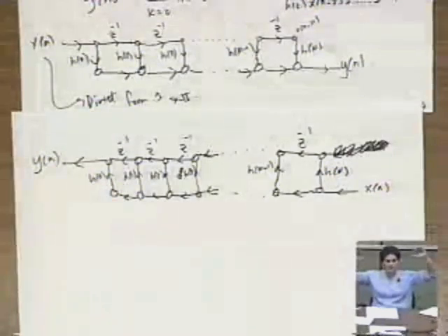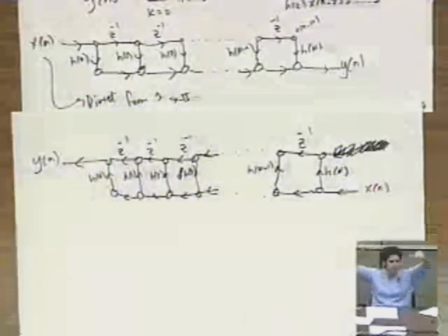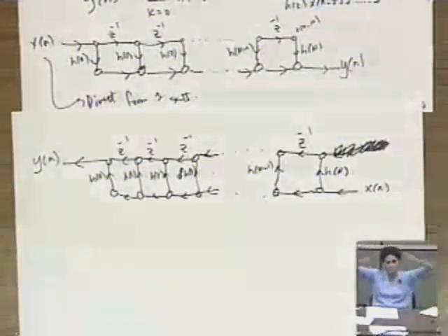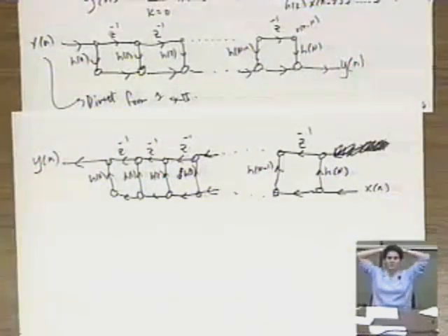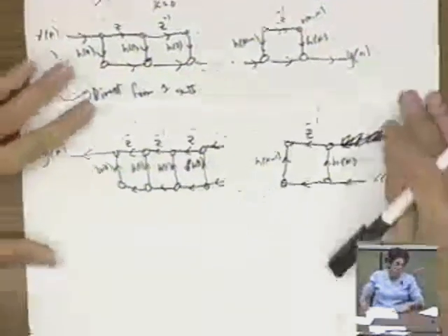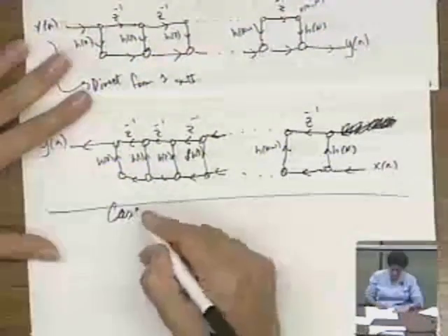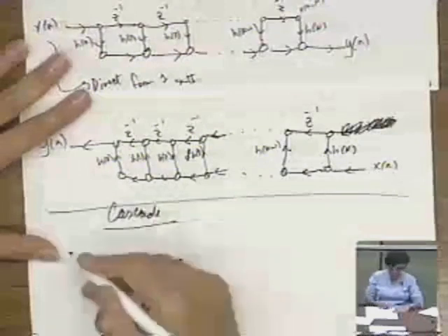Well, in the IIR case, the rational transfer function, you had a polynomial in the numerator and the denominator. You just factored it. You applied the fundamental theorem of algebra. You found the roots. You could factor the numerator, which is the polynomial, and the denominator. All that's happened now is you don't have a denominator. Our transfer function is rational, but it only has a numerator. The denominator is 1, if you will. But we can still factor the numerator and come up with a cascade structure.